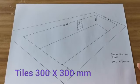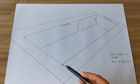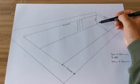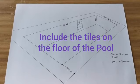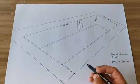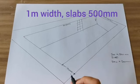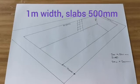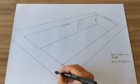What you need to do is work out how many tiles you will need to cover the inside of this pool. You've got your sizes on the outside there, but you also have 1.5 meters down there. So that will be a sum that you'll need to come up with yourselves. The other part of this, of course, is the slabs. So you'll need to work out, and this one's quite an easy one, kept the maths quite simple. We have a 1 meter width, and each slab is 500 millimeters by 500 millimeters. So you should be able to work out how many slabs that we need for the outside area of this pool.